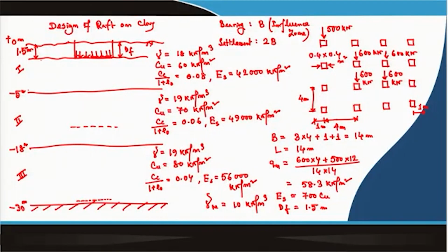So, that is why we will take our conventional bearing capacity theory by taking the weighted average of the Cu value. So, that weighted average we will take. This layer you can see is 3.5, and this one will be 10.5, because the total is 14.